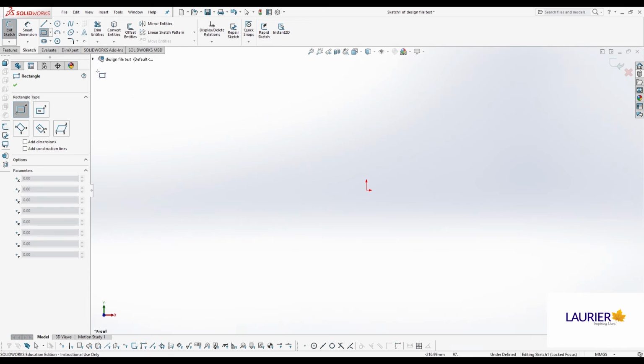This is really important. If you're looking at a piece of paper on quite an oblique angle and you've got a square drawn on it, it's really hard to tell a square from a rectangle. But if you look straight down at the piece of paper, it's very easy to tell whether that's a square or a rectangle. So it's always a good practice to look straight at anything that you're drawing in 2 dimensions. And the CAD does this for you, but fair warning, it only does it once. Every subsequent time that we go into 2D or back into 3D, we're going to have to manually reorient it.